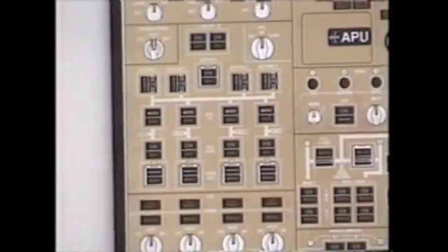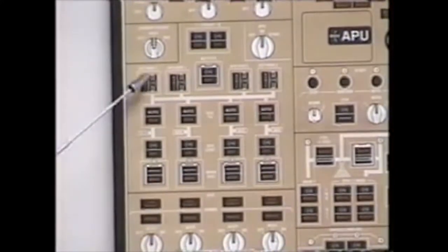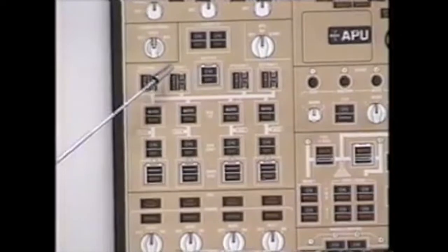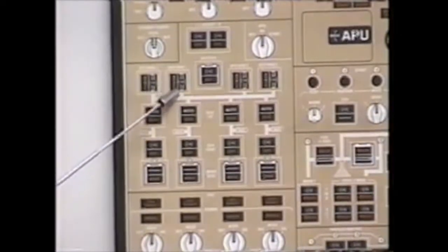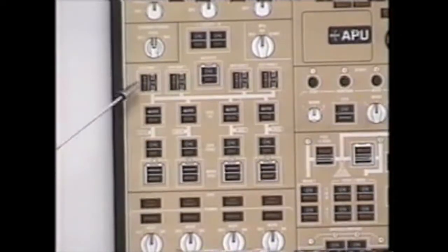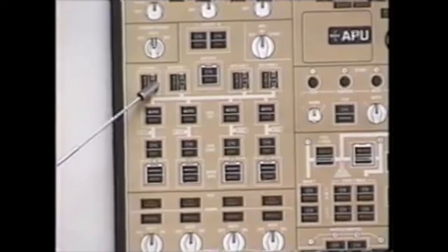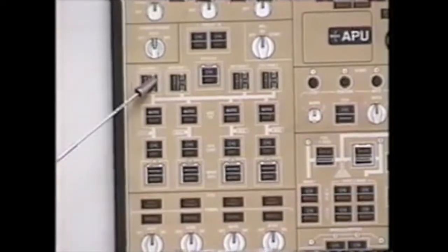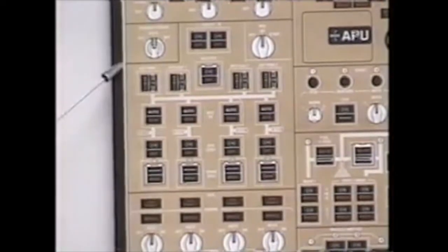The primary power source to that ground handling bus is external power number 1, backed up by APU generator number 1. Powering the ground handling bus requires the avail light or the on light in either of these 2 switches. External power needs to be plugged in. It does not need to be on. If you place external power on, it will still power the ground handling bus.